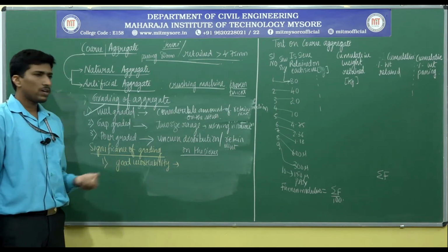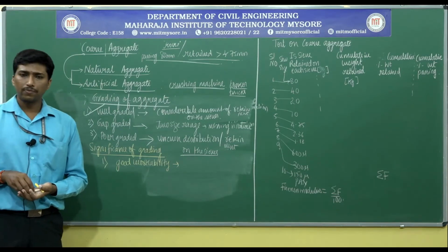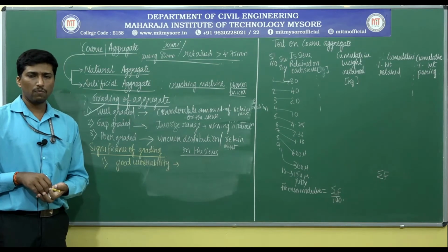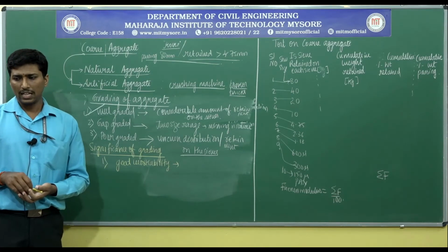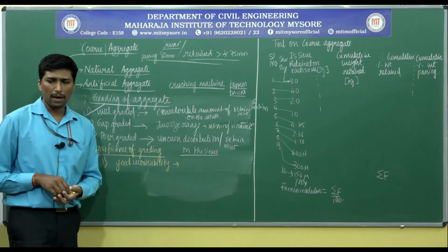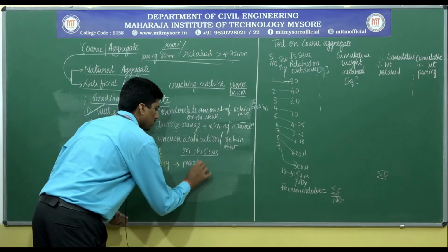Here good workability also refers to the mix of the fine aggregate, coarse aggregate, cement and water. And in this part, well graded aggregate has a maximum density when it is being compacted.